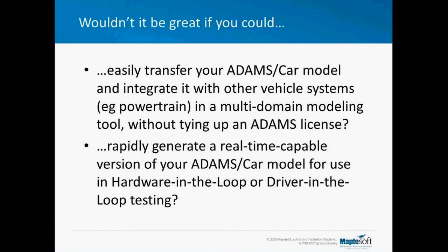And also the notion of being able to generate real-time capable code of your Adams Car model for doing hardware-in-the-loop, driver-in-the-loop, component-in-the-loop types of testing. So these are two really valuable propositions for going down this route.